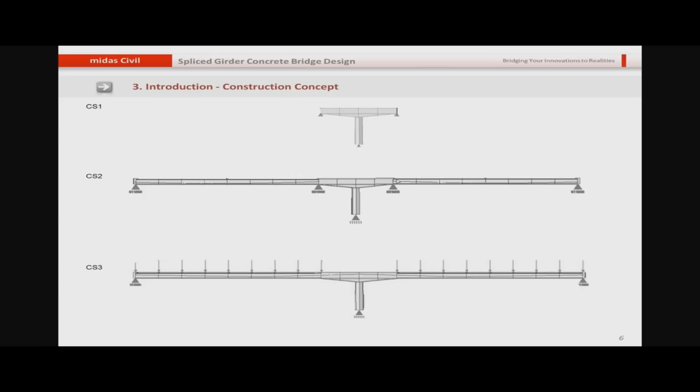And as you see, we have pre-stressed tendons, you can see them in the left and right, on these I-girders or bulb tees. But in the next stage, we have the post-tensioning tendons, and when we apply these post-tensioning tendons and pull them, we can remove this temporary support, and you can see that the bridge is completed and you can apply your load.